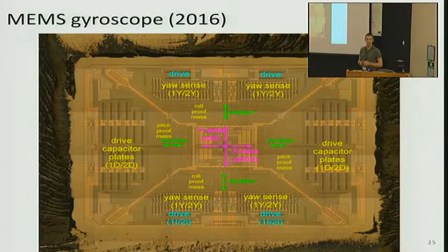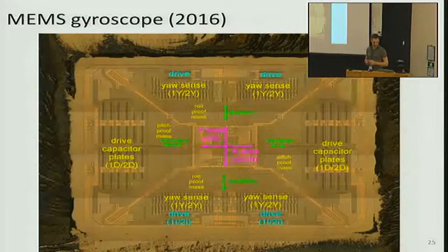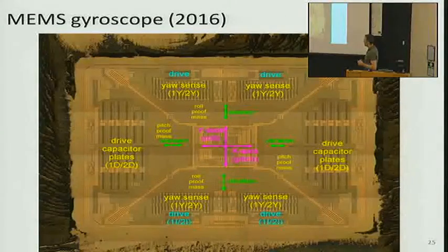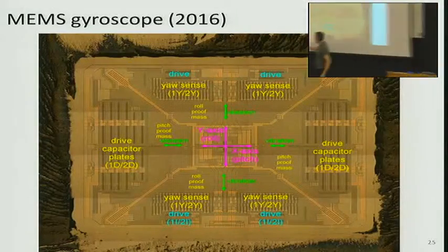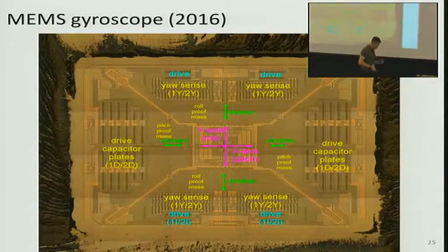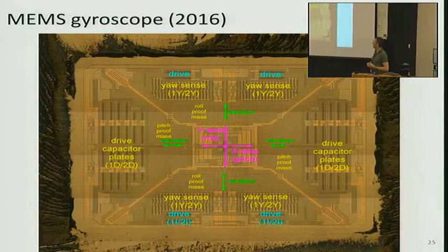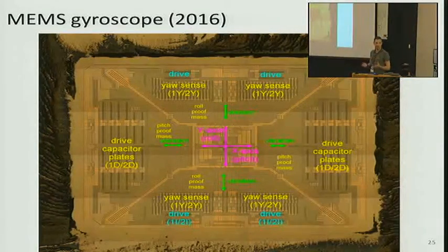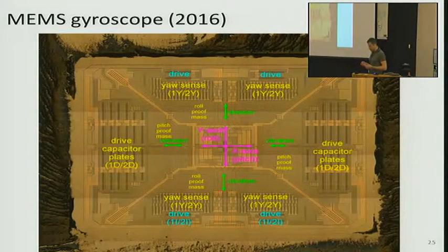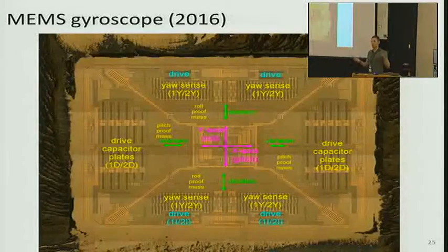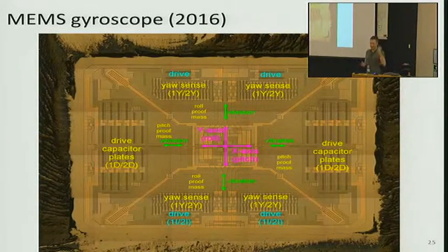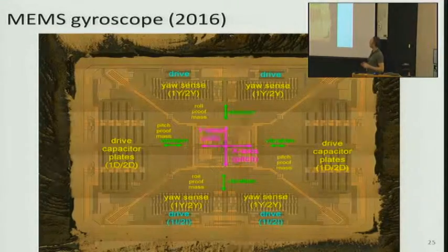Nowadays, this is what a gyroscope looks like, and it's quite a bit smaller. In terms of size, from here over to here is about 1 millimetre. And the way that it works is by a slightly different gyroscopic principle. Like if you have a tuning fork, probably people don't know what tuning forks are nowadays, but if you have a tuning fork with sort of 2 prongs on it, bang it on a hard surface and it will vibrate. If you try and rotate the tuning fork, you'll feel a slight resistance because of the Coriolis effect.